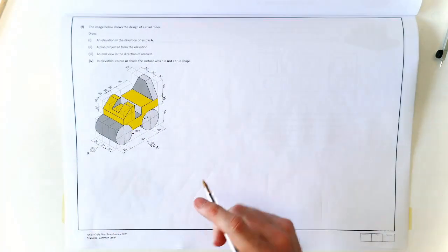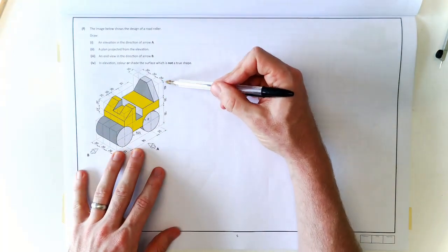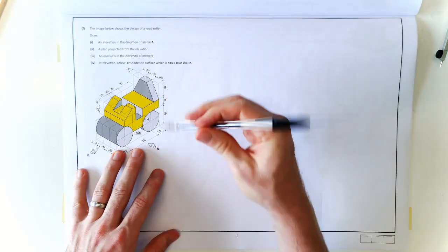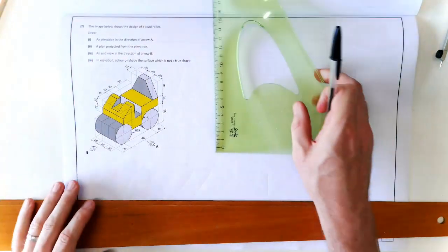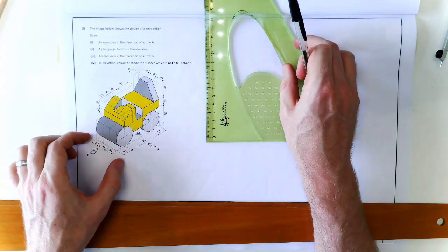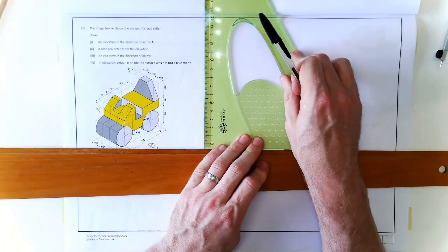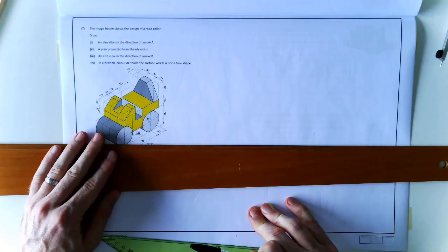So I need to come down far enough. If I look at the overall height of this, with 50 plus 20 plus 40, that's 90, 110. So I'll come down more than 110. Let's say I'll come down, what's that with 60? Yeah, I'll come down, let's say 150. That should give me plenty of space. And here's my XY line.